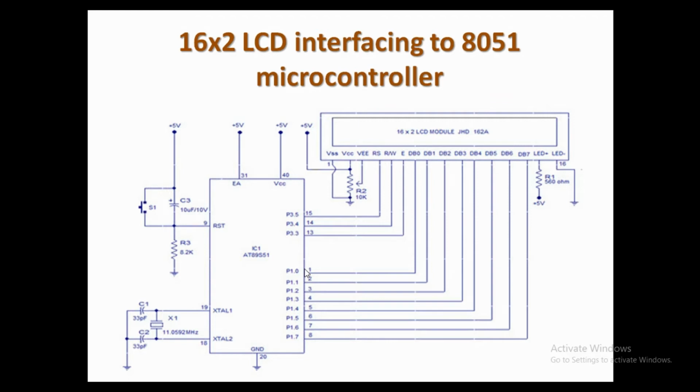These are connected to a corresponding port on the microcontroller. In this case, I'm going to be using port 1. So here we're having 8 pins. We're going to connect the 8 bits of port 1, that is from P1.0 to P1.7.